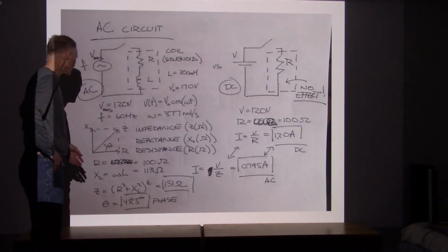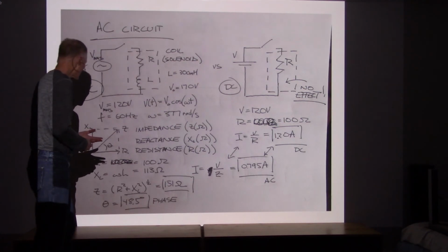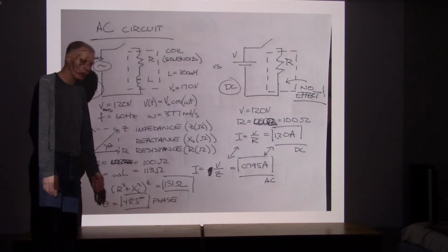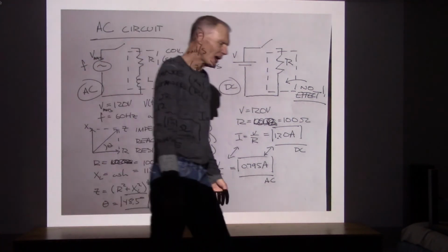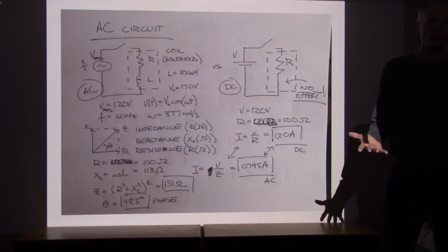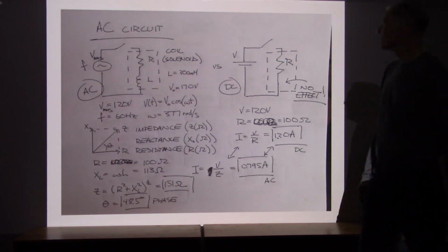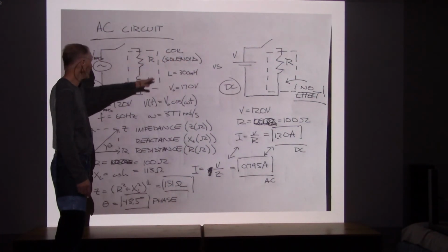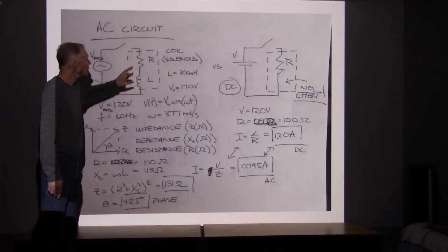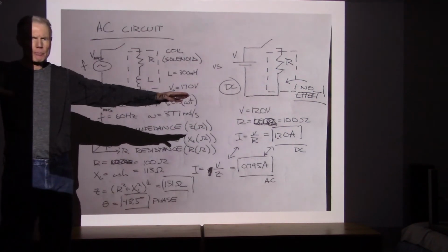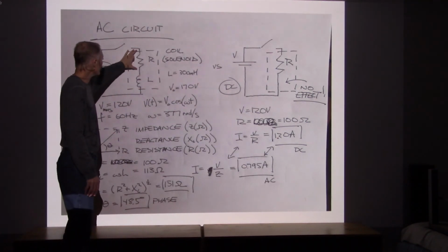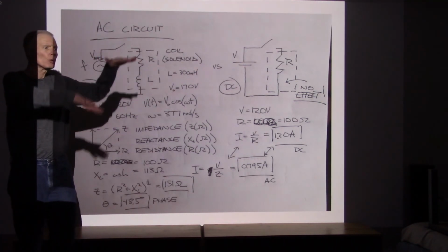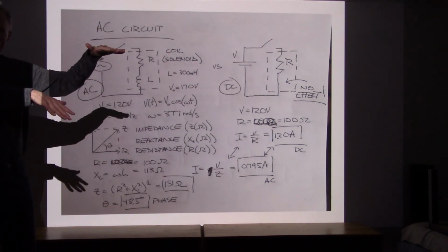So now what you might be thinking is that I just add the two resistances together, maybe it's going to be 213 ohms, but that's not true, and that's because the voltages are not in phase with each other. If I get out a voltmeter, and I can't do this because it's built into one device, but if there were some way to take that coil and separate resistance out from the inductance, and then put a voltmeter across the resistor and a voltmeter across the inductor, and then graph those, what I would see is that they're out of phase with each other.